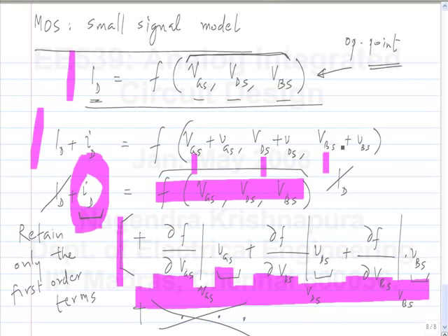And the other thing is, many times you do want the circuit to behave in a linear fashion. In fact, in those cases, effectively what you are doing is trying to make this part much more dominant compared to any other nonlinear term. In those cases also, because you deliberately try to make the circuit as linear as possible, the small signal analysis is even more valid. Small signal analysis keeps only the linear terms and throws out everything else. So if you end up with a linear circuit, then clearly it is valid.